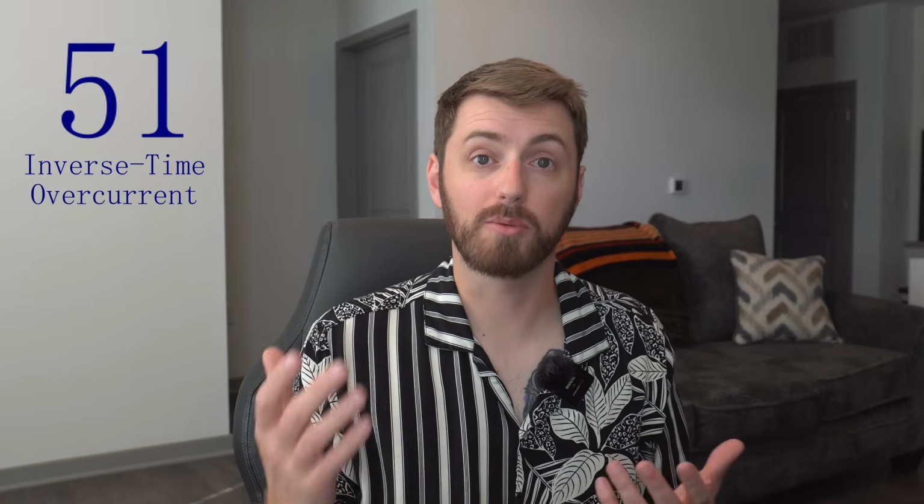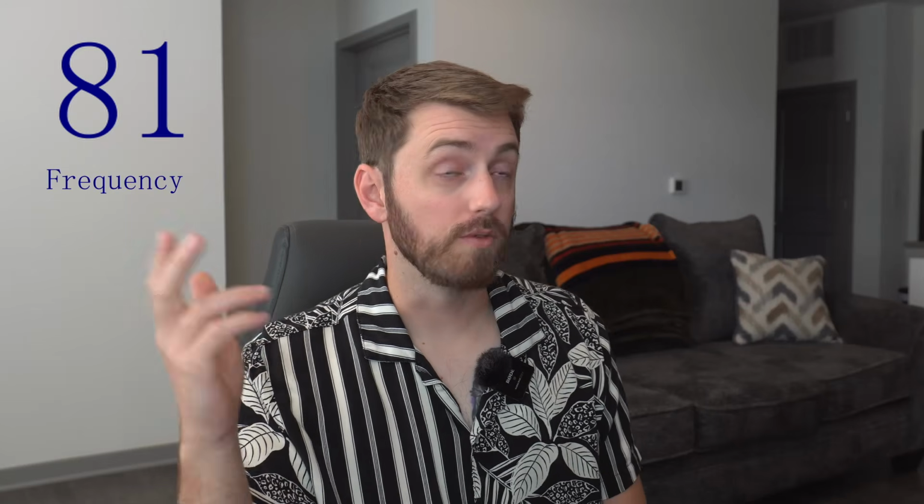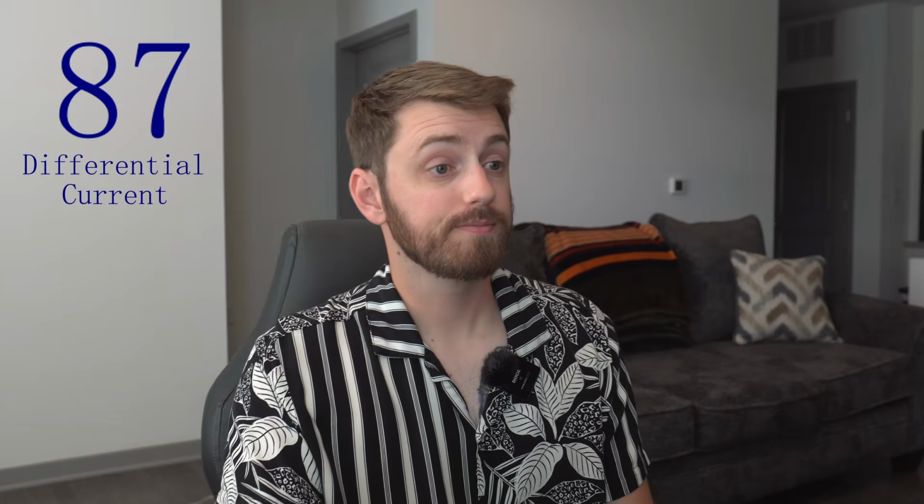51 is an inverse time overcurrent device, or like a thermal overload. 27, very common, that's under voltage. 59, slightly less common, is over voltage, which you see, 27, 59, all over the place. We'll talk about them here for the 751. 81 is frequency, either over or under frequency. 87 is differential. Again, this is just the foundation.